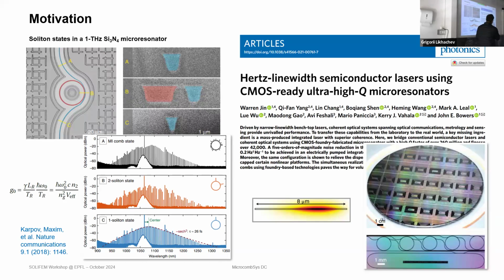And there, if your waveguide is thin like this, this is a paper by the group of John Bowers, published in Nature Photonics, heavily cited. You can see that they have a very thin waveguide, 100 nanometer thin, and you can see how wide this waveguide is, 8 micron wide, to minimize the bending loss. You can also see the scale of the whole wafer. This is 1 centimeter, so basically one device is almost a centimeter long.